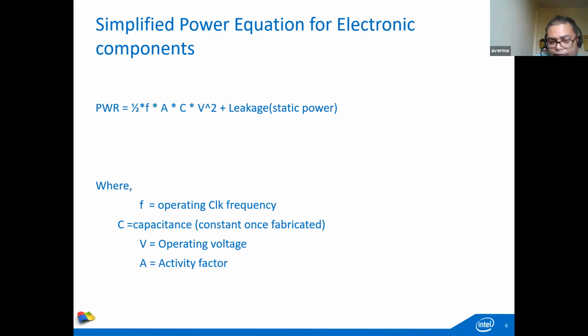This is what I was trying to explain about the activity factor. In the sleep state, you still have some activity factor for the DRAM. But in the case of hibernation, the activity factor for the DRAM is 0. Similarly, each electronic component, for example the CPU, can be on for some time when it's required and turned off when it's not required.